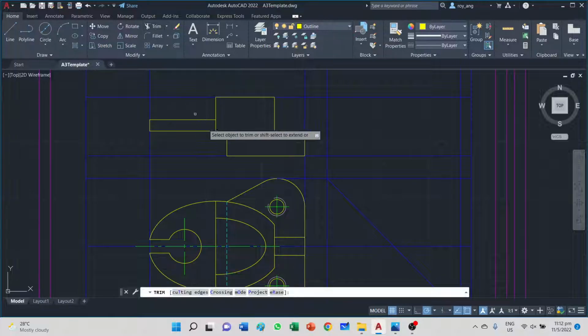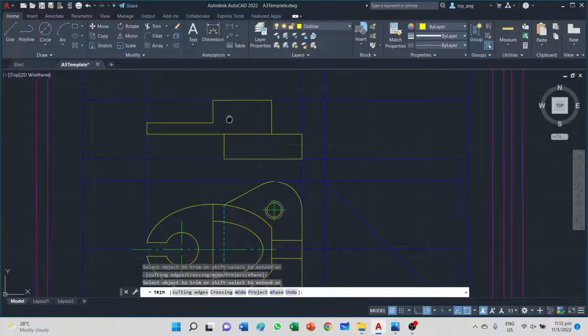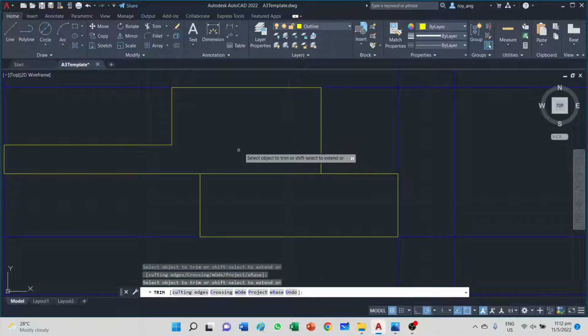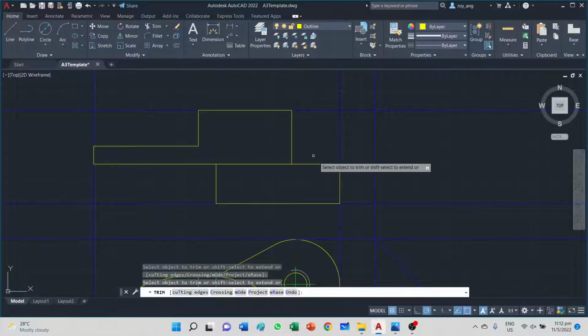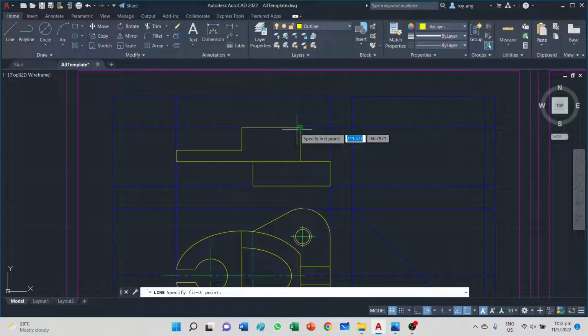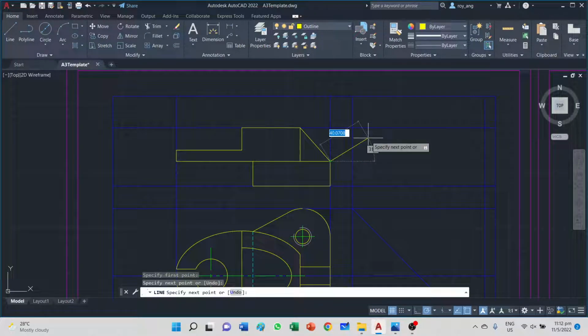This part here is a continuous surface. And is this all of my outline? Oh no, there is a web. So it may be very tempting for you to start drawing your hidden lines because you see it, and you need to kind of hold yourself back.